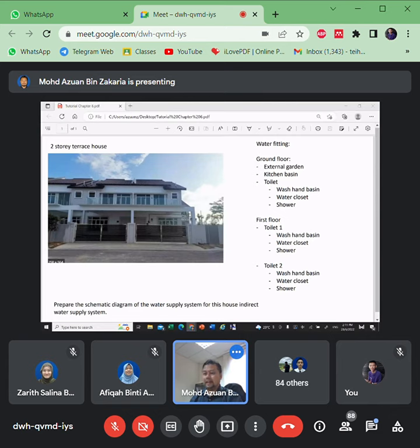Okay. And then, as I mentioned before, this is the typical type of indirect water distribution. At least one to the kitchen, and then the rest through the tank, and then the tank will distribute to all the fittings by distribution pipe. Alright. Another type is direct water, which has no tank, basically a simple way. And the advantage is that when we use direct water, all fittings have access to potable water, right? And the pressure of water is slightly higher compared to indirect water supply.